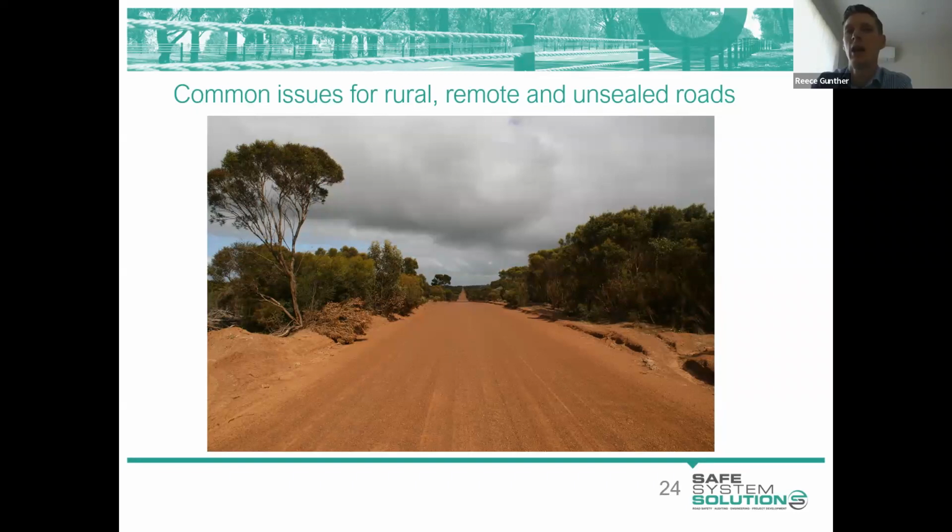We also meander our road network, particularly when driving east or west. I'm saying east or west because the sun rises and sets in those locations, which can impact driver visibility of the road. So we sort of meander the road to give people a break or rest their eyes, as opposed to driving straight head on into a sunset or a sunrise. We do consider those in the planning stage. It should be something that is considered for those long distance trips.